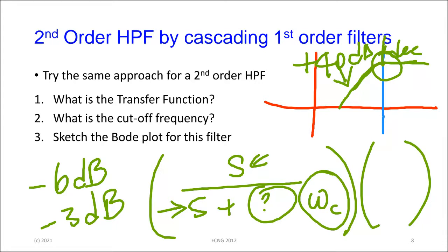The trade-off is that you're going to have an extra op-amp. Not too much of an issue most times, because you can get double op-amps on the same chip anyway. It does depend, as I say, on the particular application that is being used for. If price is an issue, then you want to reduce the number of components on it.